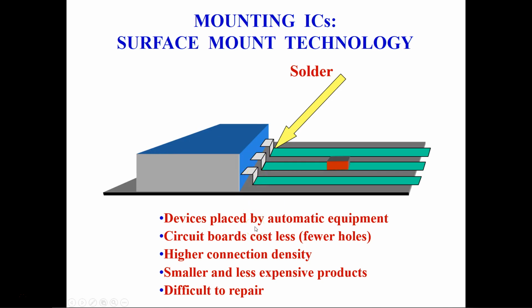So repair is difficult in the case of surface mount technology, but it is a much better approach to make a circuit, because you can utilize the board and put more components, and your design can be more compact.